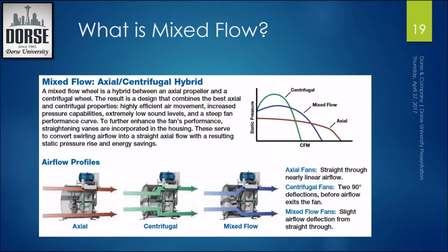Oftentimes you can select a mixed flow fan at lower noise, lower horsepower, and a smaller fan size than an inline centrifugal.